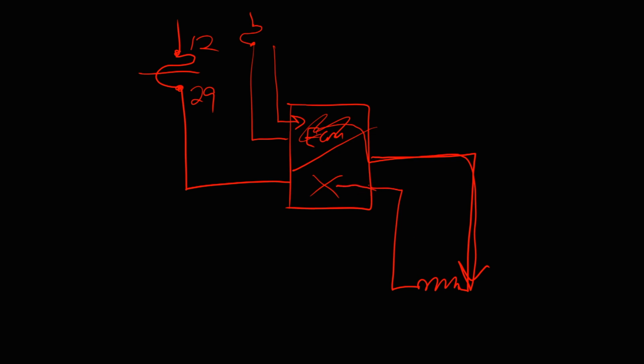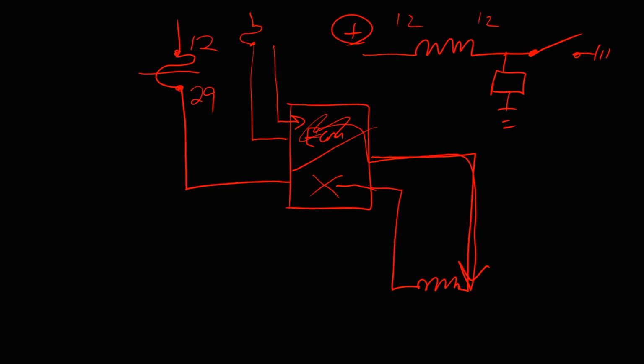So I don't know if you guys covered it to this level yet, but let me just show you real quick. Fuel injector, solenoid, relay coil, whatever it is, I'm measuring right here. What does this look like? If I looked at a scope waveform, circuit off, we already covered this. It's 12 and 12, right? So start my line right here, it's 12 volts.